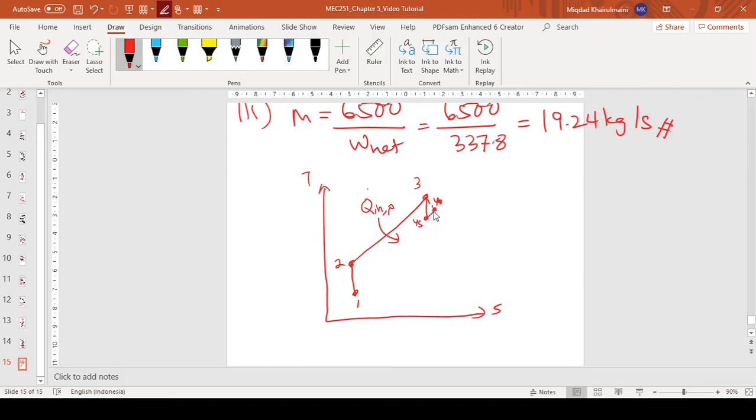This will be the same pressure. Reheat it to the same temperature here, state 5, and then we expand it. This is the ideal state 6S, but there is also an isentropic efficiency, and then from state 1 to state 6 we connect the heat rejection process. So this is the TS diagram for the question.